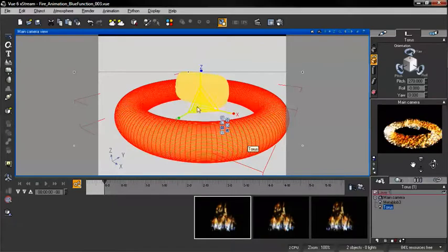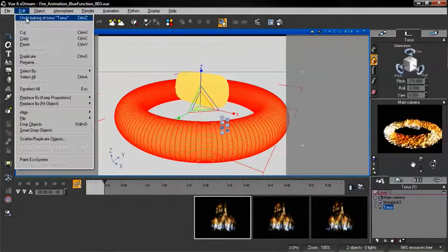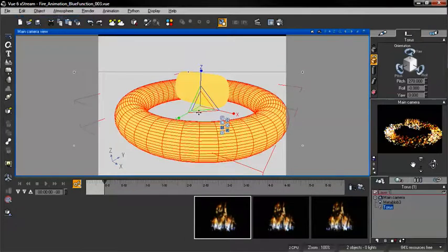But we can still see the overall orientation of our object is still the same. So we could either use a meta blob, and that will change it, or we can alter the material itself, editing its rotation options. But once you're working with a material animated surface, that's going to be difficult to do. And I actually want to add a little bit of variation to this anyway, so we're going to use a meta blob. So I can undo the bake that we just did,